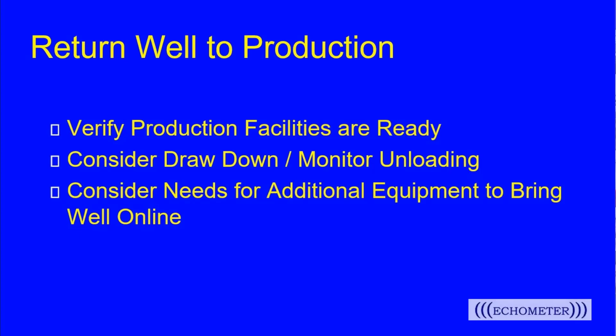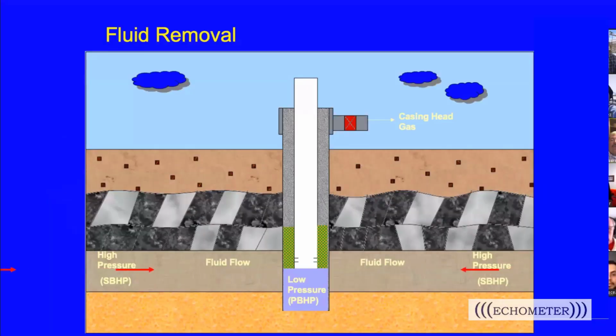Soap sticks won't really help when the well's shut in because you don't have the flow to create the foam, the bubbles with the soap stick. But perhaps once it's going again, that may help unload some of the liquids that have accumulated in the well. But we're really after getting our static bottom hole pressure.